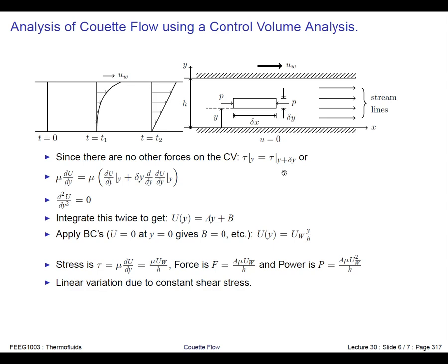Okay, so here's my force balance over my CV. I've said that the pressure forces are 0, so I can say that this term is equal to this term, and the du by dy cancels out, and I can also cancel out the viscosities, and I end up with this governing equation. So I hope you appreciate why we needed to talk about Stokes' first problem, because the viscosity has no effect on the steady state solution. It only controls the rate at which we can get there.